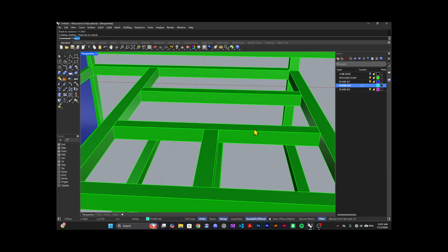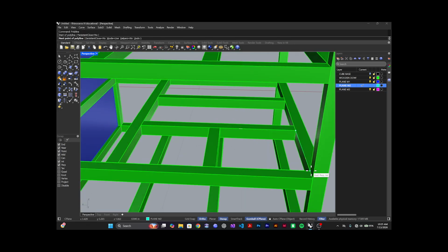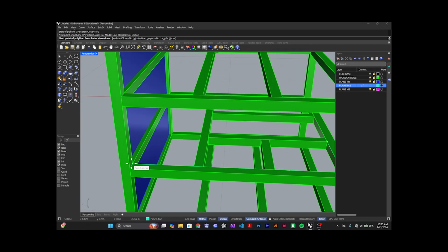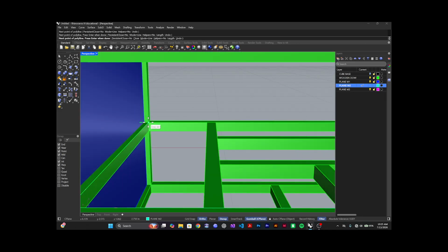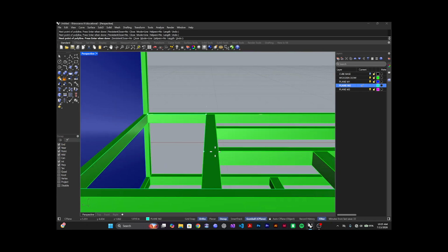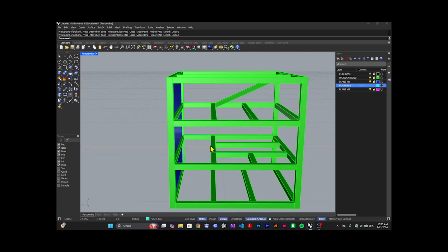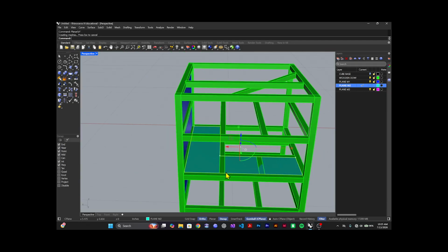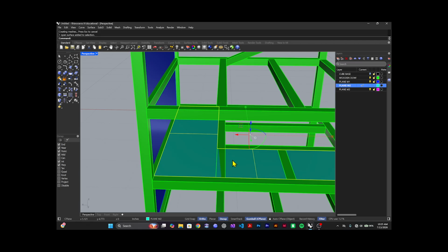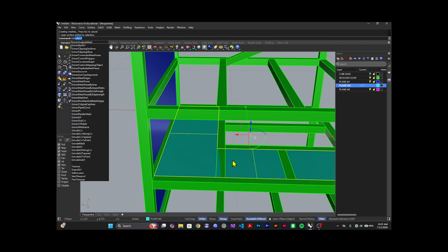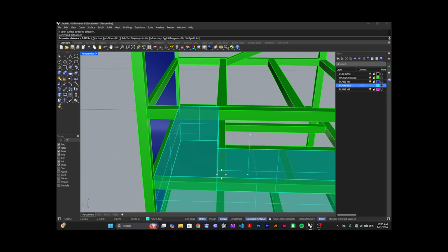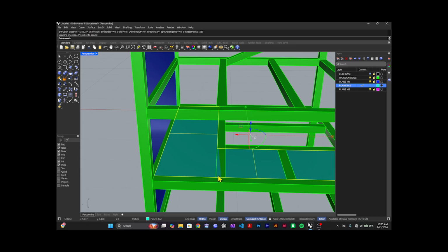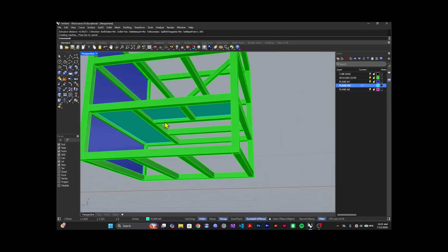So again, polyline, not polygon, polyline, and then I'm gonna have one right here. Remember to be working in different layers. Okay, so let's say that I want one right there, right? And then again, planar surface, enter, and then we select the surface, and then extrude surface. Again, let's go down. In this case, sorry, it's 0.0625. Right, so that's how you guys do your planes.